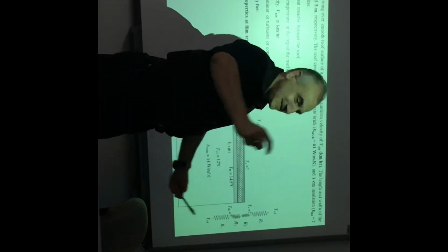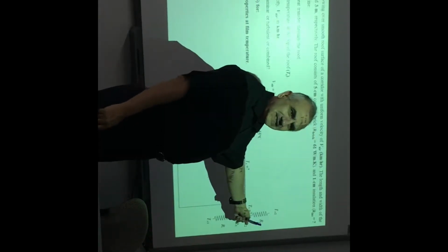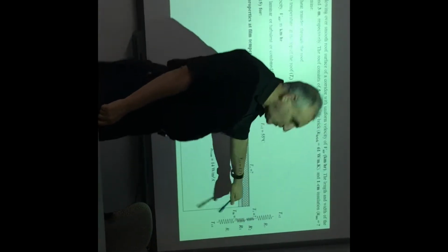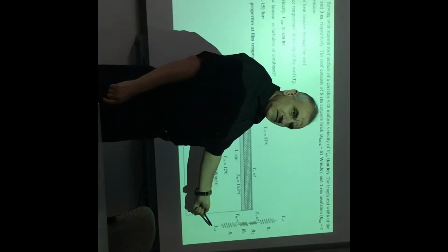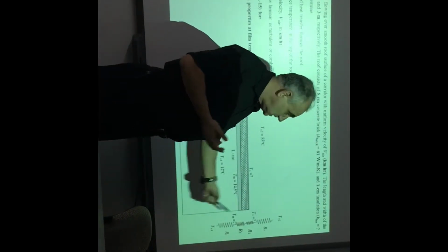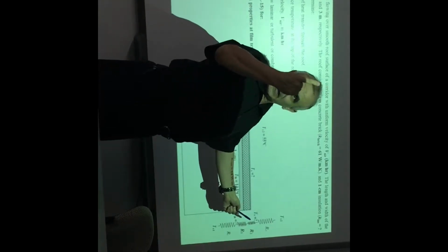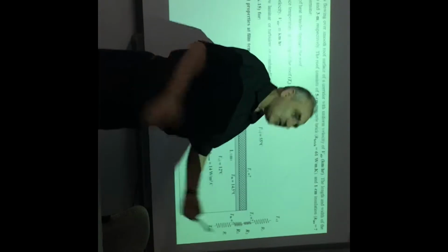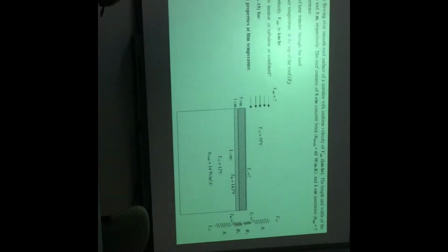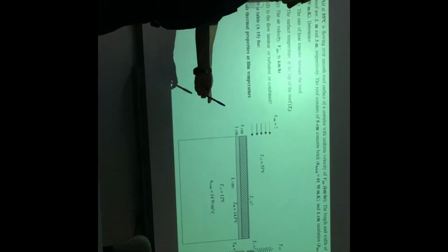So you have two unknowns, T surface and the resistance. However, if you go from the bottom, T surface minus T fluid 1, T fluid 1 is known and T surface is unknown, so now you have one unknown, divided by the resistances R2, R1 and Ri, all of them known. Remember, why known?